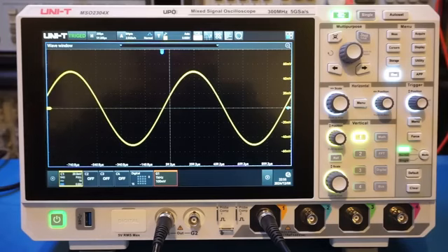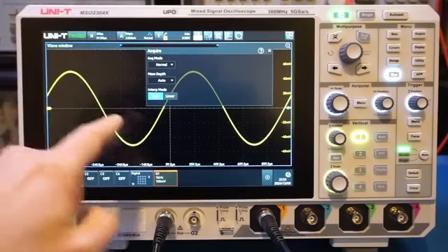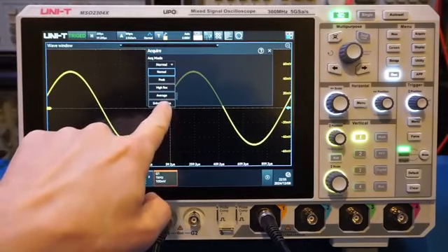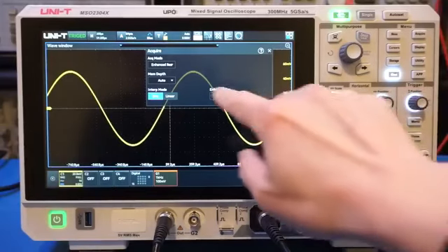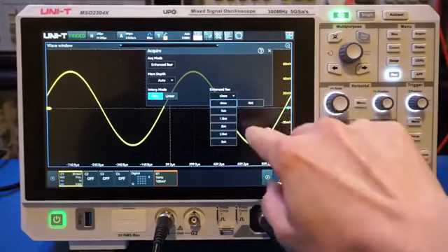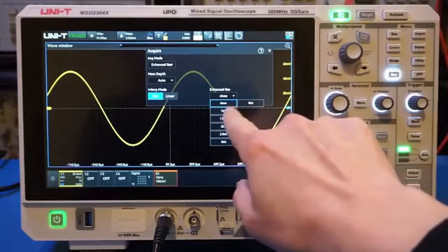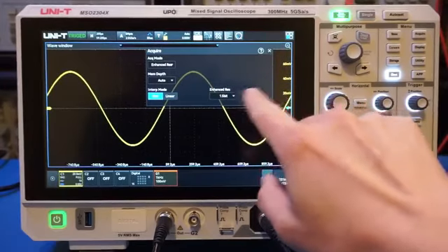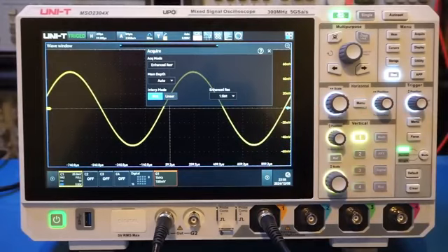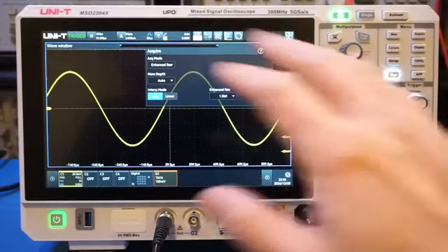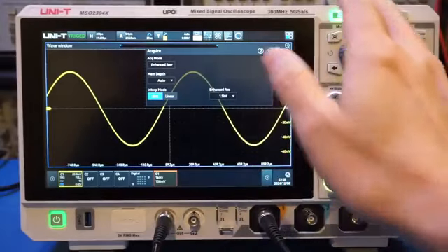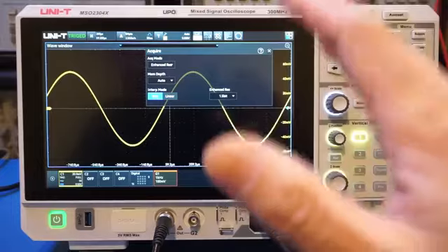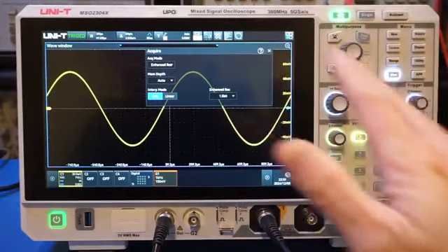And to change the setting, that's in the acquisition menu. So you can come here, you can see here, the acquisition mode right now is normal. Of course, we can change it to enhanced resolution. And now you can see we have this enhanced resolution combo box. Let's drop it down. You can see here you can do 1 additional bit, and you can do 1.5 bits, so on and so forth. And the trade-off here is the available bandwidth that can be achieved. You can see that you can actually achieve an additional 1.5 bits resolution without incurring any bandwidth penalty, but the acquisition speed probably will be impacted. I'm just guessing here, of course. Now, I can verify that a little bit later if I remember.